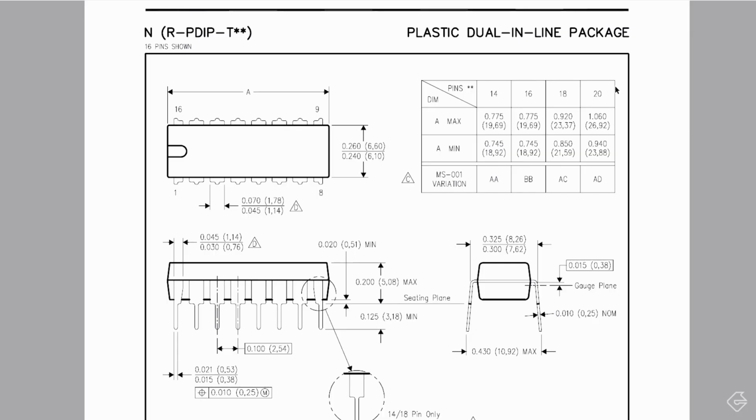Here's another data sheet of an IC that we're using. This is a 4049 IC. And if you look at this, you can actually see that these leads are square. They're not round, they're square. So one dimension of those leads says that it's 0.25 millimeters thick. Another dimension right down here says that this is 0.53 millimeters thick. So that's actually not a square, it's a rectangle.